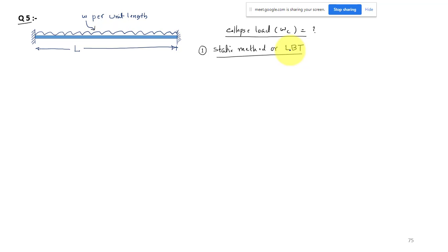In this theorem we have to know the moment diagram, or at least the shape of the moment diagram. In simple cases we will know the standard formula also, and we can make use of that. For the fixed beam, we know this will be the bending moment diagram. We'll have a rectangular diagram, that is the fixed end moment, and the free moment diagram.